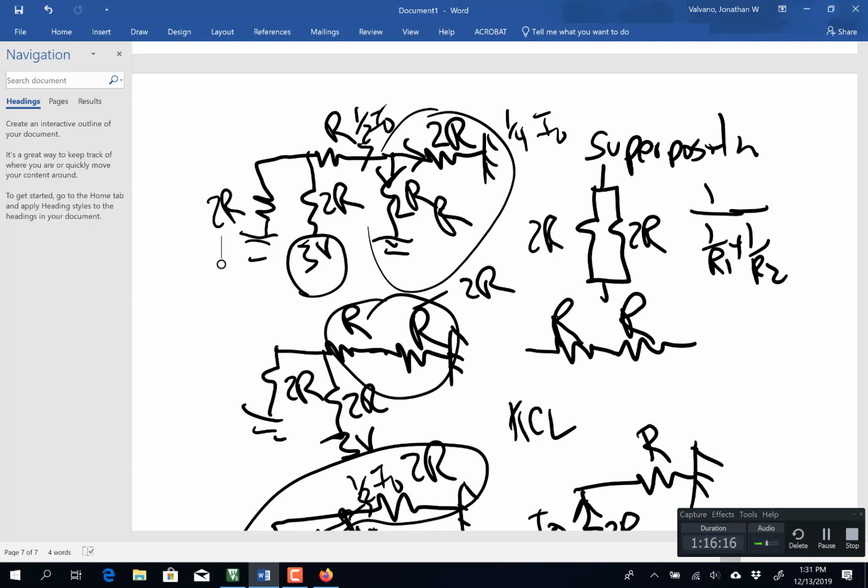So this is a little bit complicated. Kids don't do very well on it, but I promise you the things I am going to ask you are for you to understand the law of superposition, which is to take the signals one at a time, and all the other voltages we're going to short to 0, to ground.